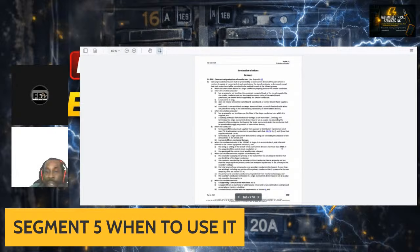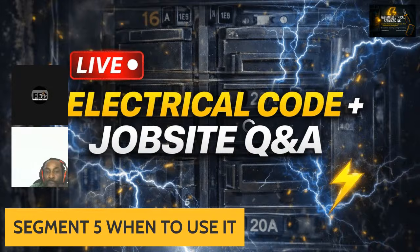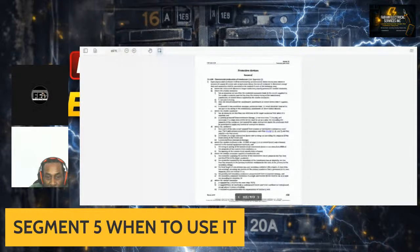The total length of one primary plus one secondary conductor, the longest if more than one winding, excluding any portion of the primary conductor that is protected at its own ampacity, does not exceed 7.5 meters. So that 7.5 meters, again, is used on the job site, and you will see it again once I go further down into the code book.